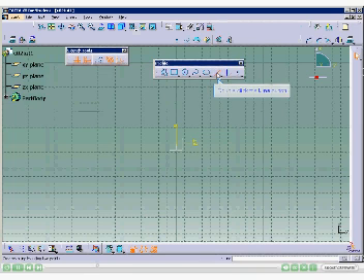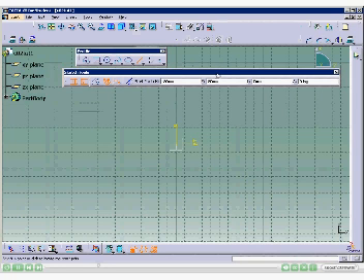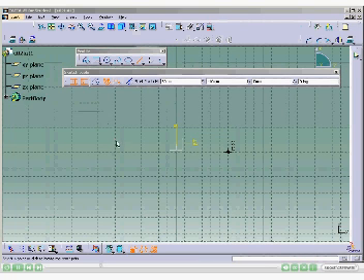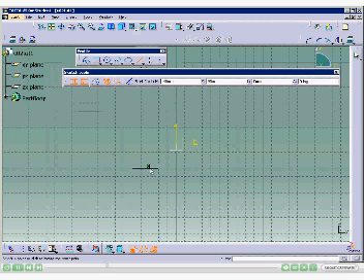Now double-click on the Line tool. Choose the Snap to Point button from the Sketch Tools toolbar, if it is not chosen. Move the cursor in the third quadrant. The coordinates of the point will be displayed along with the cursor. Click at the point whose coordinates are -50 mm, -30 mm. Next, move the cursor horizontally toward the right. You will notice that the color of the line turns blue. Move the cursor until the length of the line is shown as 30 mm in the Edit box of the Sketch Tools toolbar, or you can enter 30 directly in the Edit box.